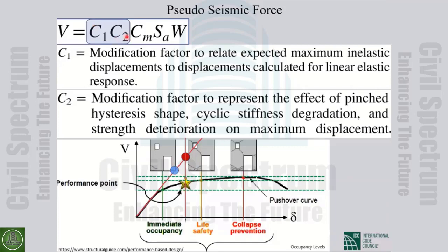These two coefficients are there to increase the base shear if needed, so that when you put this base shear in your elastic model, you get the same displacement as the building experiences in the earthquake. Why is this important for us, and not this one? We increase this and distort this to get this one correct.